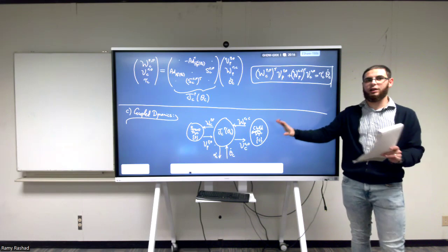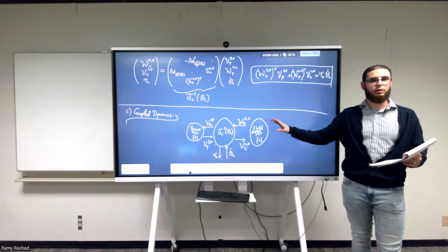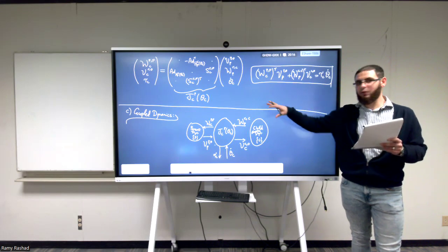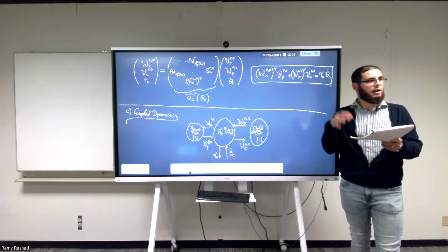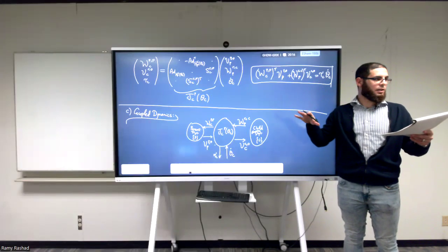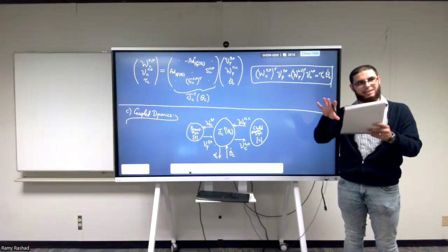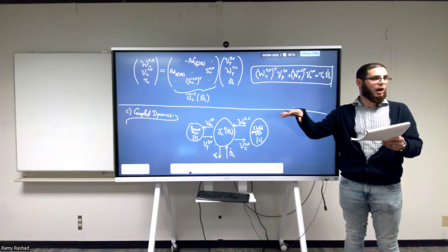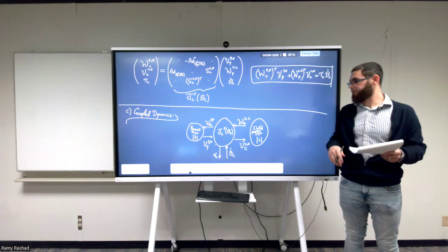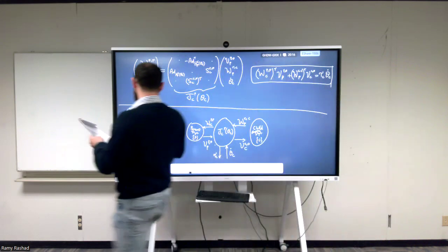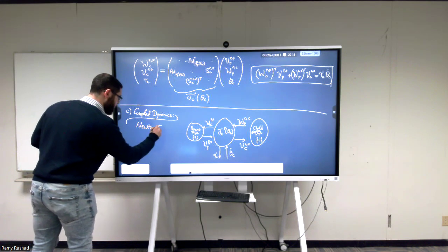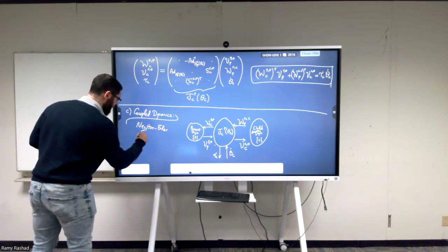Again, this doesn't work in the computer, by the way. There are a lot of problems with it. We're only writing this in this way because we're going to be using this inverse dynamics part as part of an algorithm to try to write the manipulator equations in the end. So this is only a stepping stone for us to derive the actual equations of motion. Because this is not usable at all. And this is known as the Newton-Euler inverse dynamics.